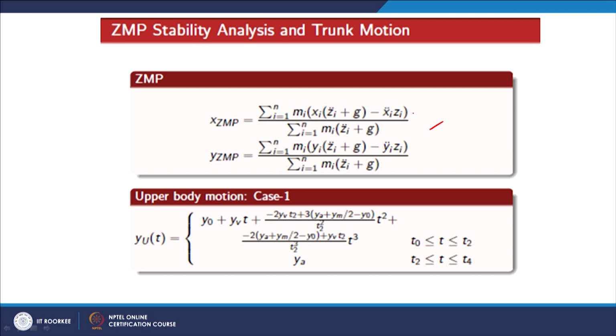Here we can also add to the previous formula. We had one more term, that is summation of mi, summation of I, the inertia multiplied by omega Iy double dot. But here we need not have this, because we are considering the entire motion as x, y, z linear motion, and the rotational motion is not considered, because the trajectory itself is giving the position x, y, z at each instant of time as a linear motion.